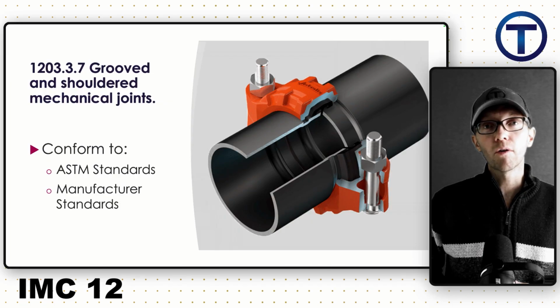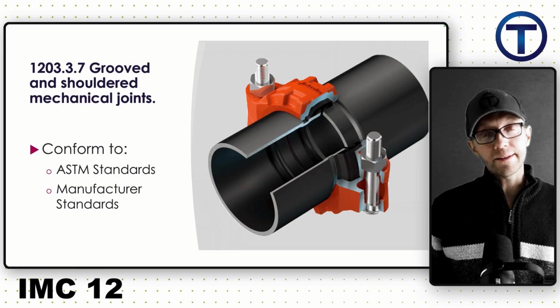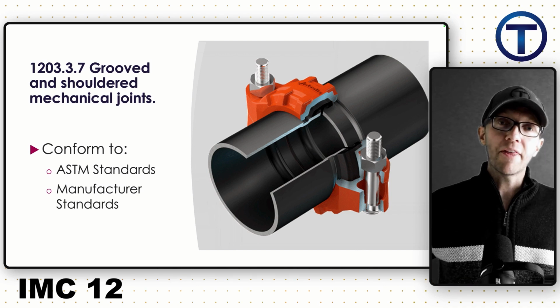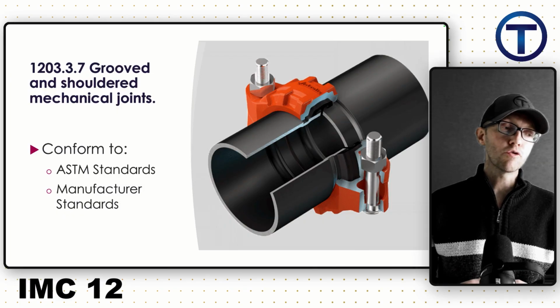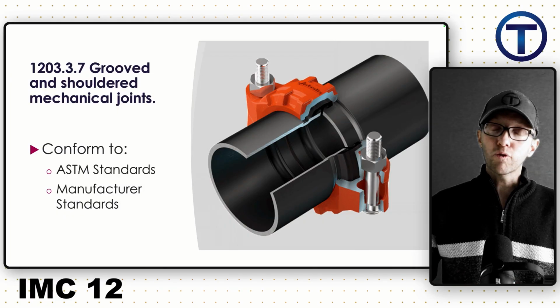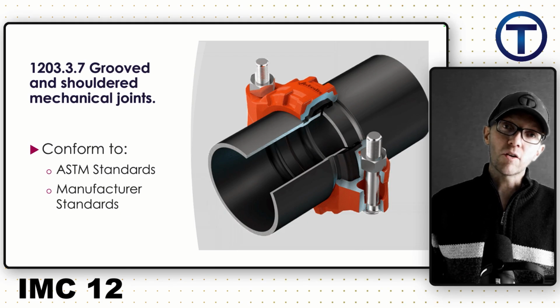Victaulic is one of the earlier companies that developed this and marketed this. But as a side note, Victaulic is just a brand name. It's not like the method itself. We'll call this the grooved and shoulder mechanical joint. These joints have to meet the ASTM standards, and of course you'd want to follow the manufacturer standards on how this is to be installed and assembled.